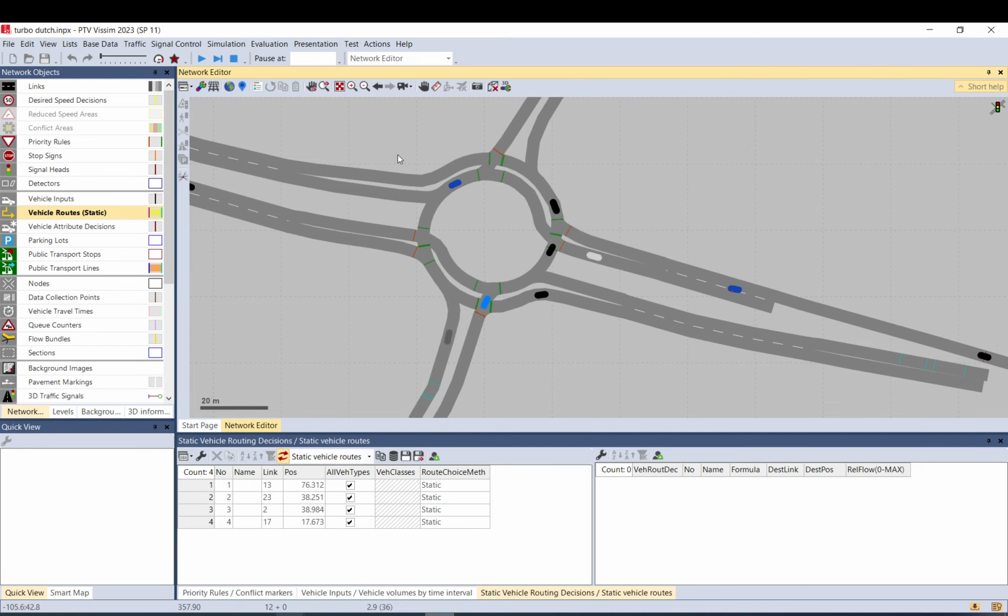If you hold down space, it will slow down the simulation. No, it looks all right. Again, if I miss something, it's possible. That's why it's good to observe the run. And if you see that some vehicle should give a bit less aggressive, you can just increase those gap times.